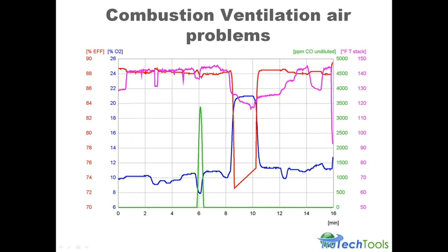This is at LMHA, which is a housing authority in Cleveland. So I went out there with a contractor having trouble with nuisance trips on the boiler pressure switch on this appliance. It's a 90-plus boiler, right? So you can see right here when that oxygen level all of a sudden dropped down to 8, this boiler went from 0 ppm CO all the way up to 3,500 ppm when I pulled it out of the stack, right? And that's why my O2, the blue line, goes up to 21% again. Because all of a sudden I looked at my analyzer and it's going up to 3,500 parts per million. I'm like, oh, crud, I don't want to ruin the cell in this thing. So I grabbed the probe, pulled it out of the stack, and the CO drops back down because it's in fresh ambient air. The O2 goes back up, right?